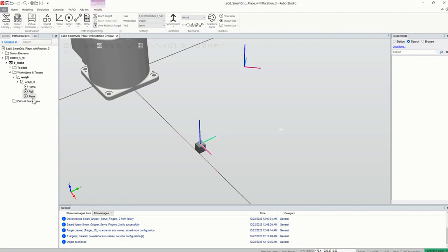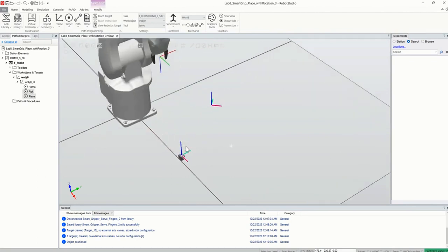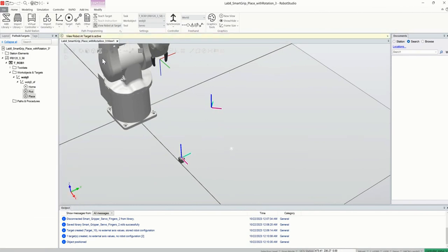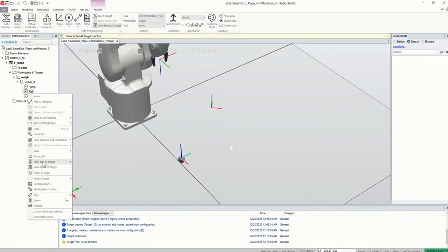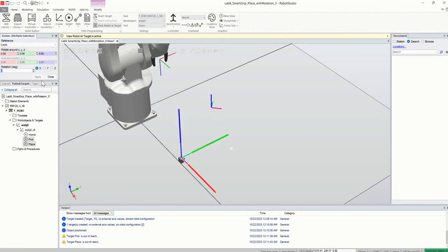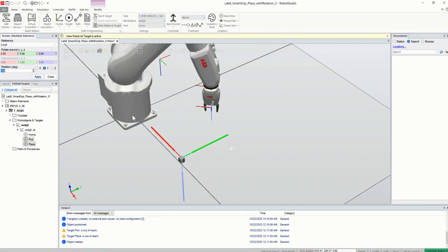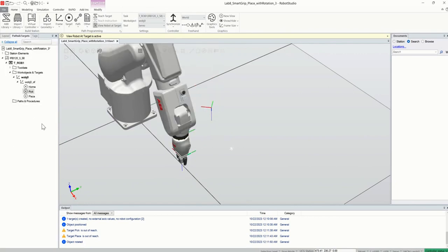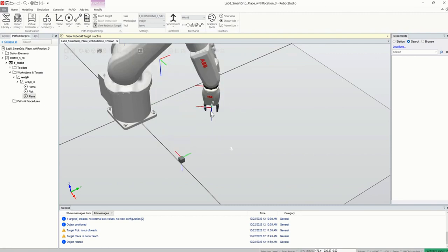I know both of them actually have their z-axis opposite of this one, right? So if you want to see that, you will see it is not showing because it's active. No worries. I would need to change both of them, so I'm just rotating with respect to the y-axis by 180 and applying them. That's how I got it. You see now you're getting that piece. This is my peak position, and that is my place position.